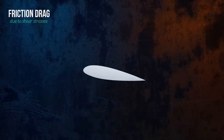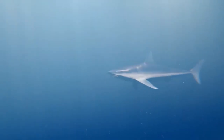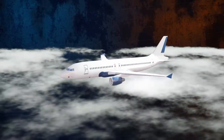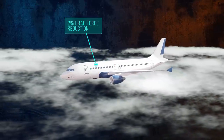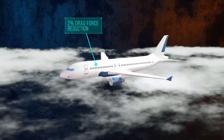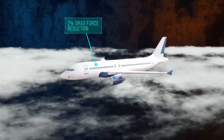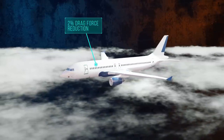When trying to minimize drag, engineers very often look to nature for inspiration. Sharks are a particular interest because of the unique microstructure of their skin. Shark scales contain microscopic ridges, which are aligned with the direction of flow. These ridges modify the turbulent boundary layer in the near wall area, and this has the effect of reducing friction drag. Research indicates that coating a commercial airliner with artificial shark skin of similar microstructure could reduce its total drag force by 2%, which would result in massive fuel savings for the industry. This approach has yet to be widely implemented on commercial aircraft, partly due to challenges associated with manufacturing, but this could change as the technology improves.